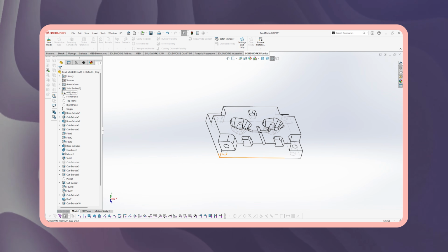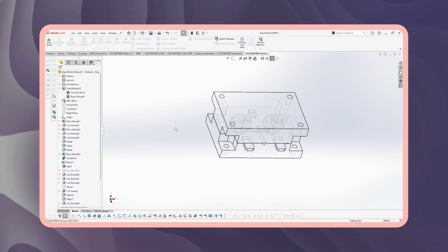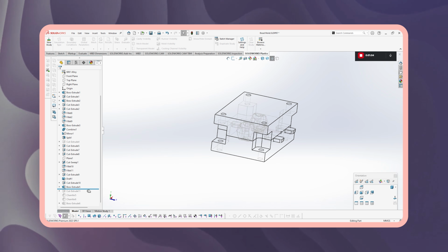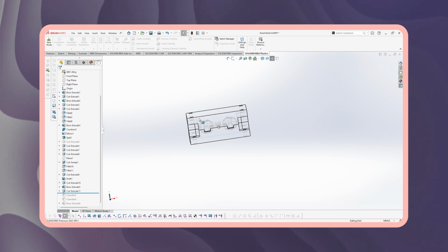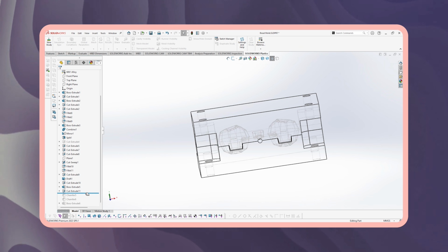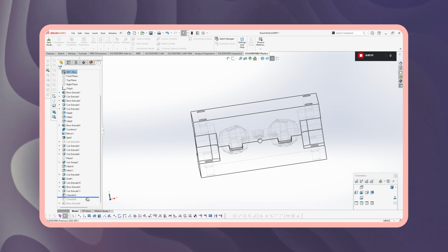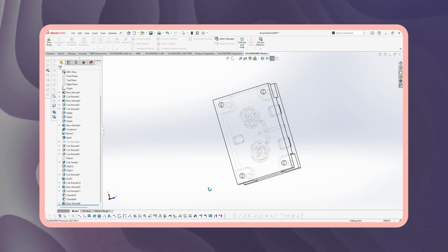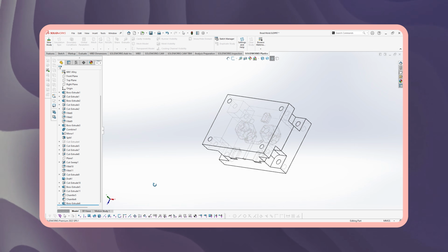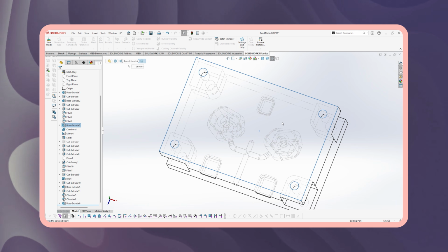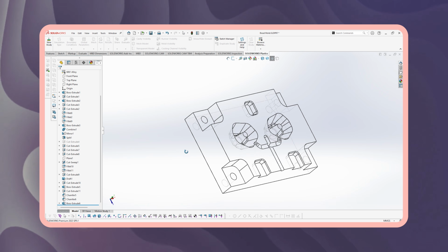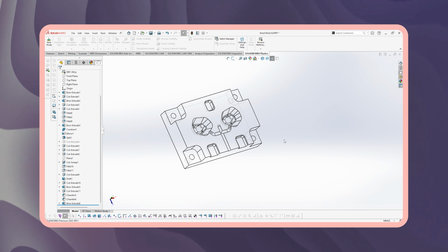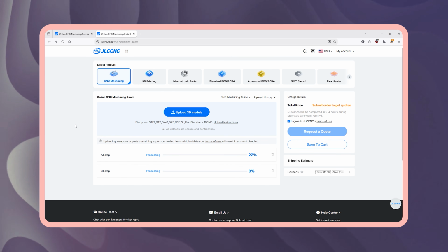For a small hand injection molding setup and polypropylene parts, aluminum is actually a very good option. It machines faster, costs less, and is perfectly suitable for this kind of production. Also, this isn't a high precision production mold. The machining here is done with standard CNC tolerances, not mold grade precision. So I had to design this as a CNC machine part that functions like a mold rather than relying on extremely tight tolerances from the machining process itself.